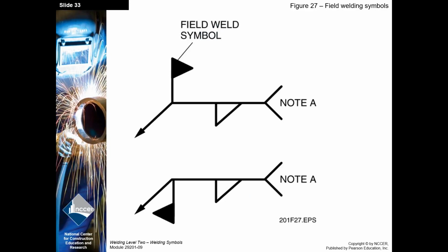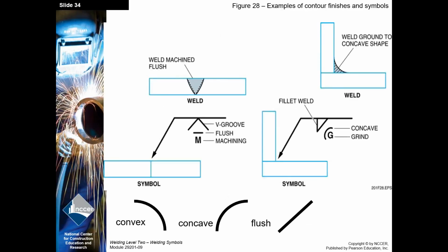There's your field weld symbol. Again, the flag can be up or down, and it can blow left or right. It should be a triangular flag, though. Don't draw any square American flags.